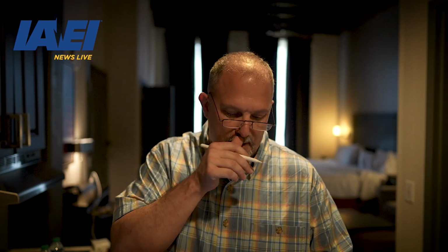The service entrance conductor, the service entrance conductors overhead system. Service conductors between the terminals of the service equipment and a point, usually outside the building, clear of building walls, where joined by tap or splice, etc. Okay, so we're basically walking through your service equipment from the utility down to the connection of the structure, and we're understanding each of the parts and pieces of that system.